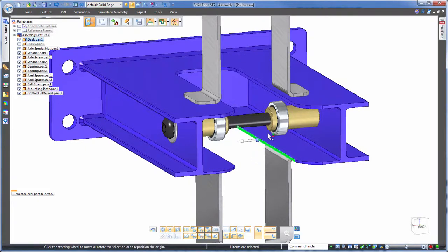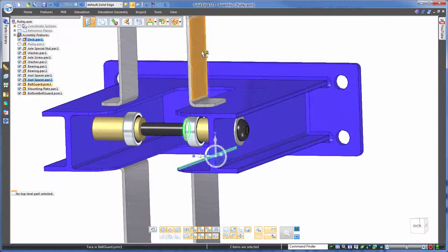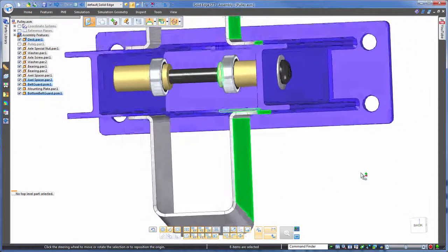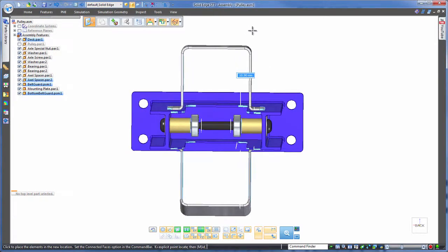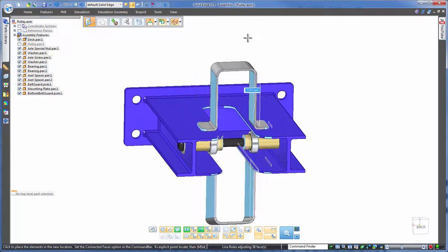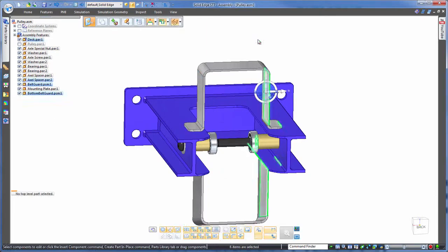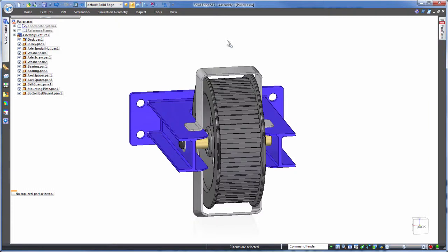Here we can modify not just one, or two, or even three, but let's edit 4, 5, and 6 different aspects from 4 individual parts. And still, Solid Edge is automatically seeing that this design is symmetrical, so actually it's doing double these edits for us. And also notice how everything else is changing sensibly. Tangent relations and wall thicknesses, for example, are all being maintained. That's what we mean by one-shot multi-part editing.